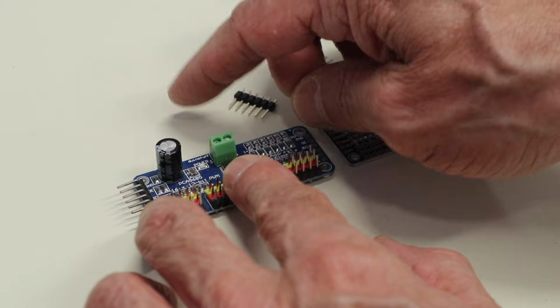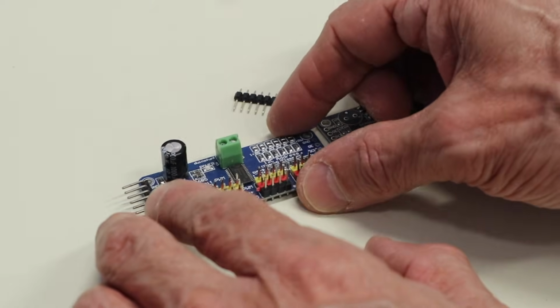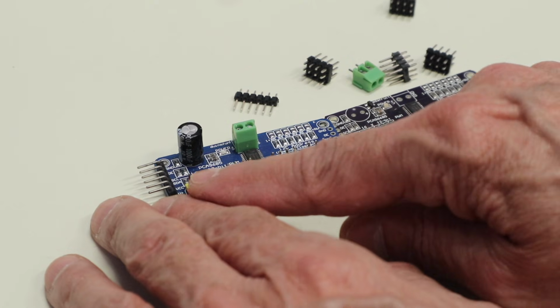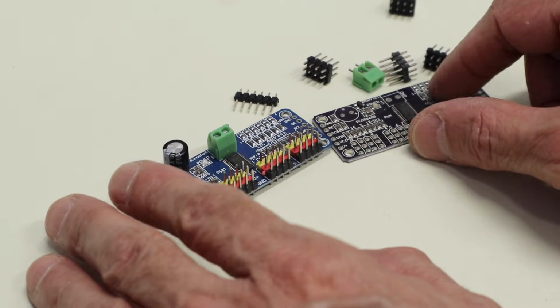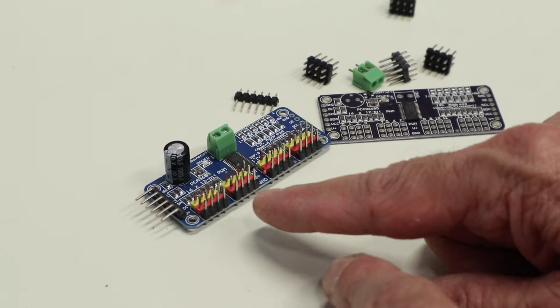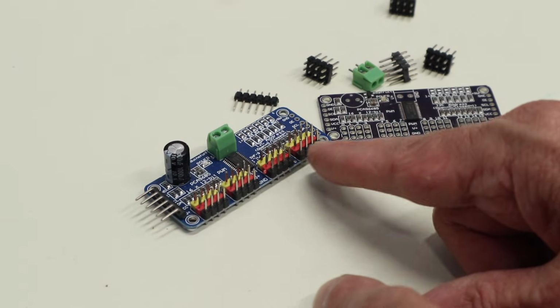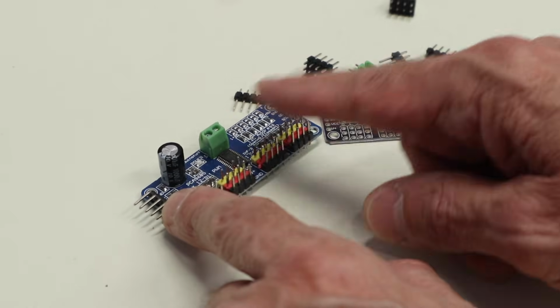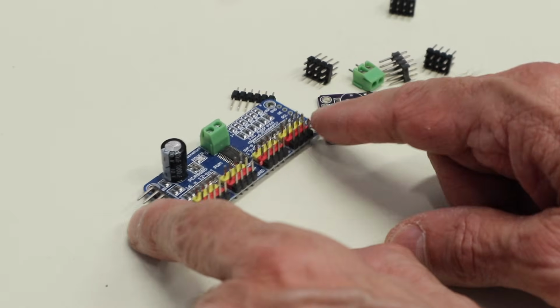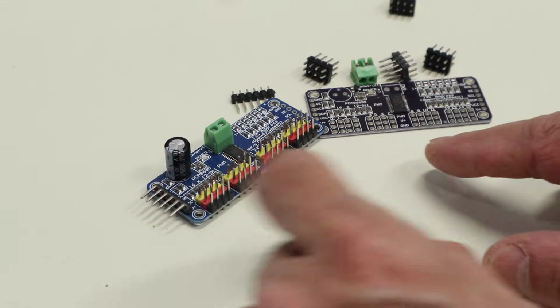So you're going to want to use a power supply that has enough capability to power all of your motors. And here, of course, is where you attach the servos. Now, this board can also be used for purposes other than servo motors. It's quite common to use this with LEDs as well and use PWM to drive them. So you can attach LEDs or LED strips onto this as well. So a very versatile and useful board.